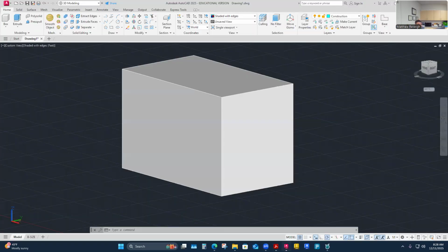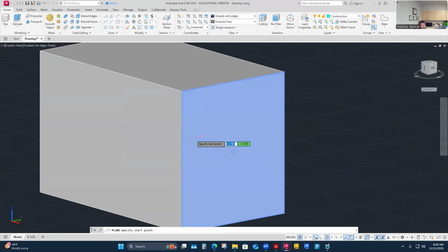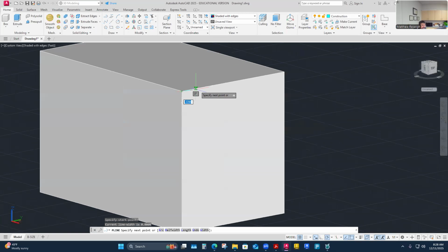So what I'm thinking is, on this surface, I'm going to cut this out, 1 and 3/4 by 2 right here, and I'm going to go in so far. I'll just do the sketch first. I'll do a polyline sketch on my construction layer on this surface, from this corner along this surface. This is the way that it's 1 and 3/4, right? 1.75, and then it's going to come down 2 inches, and then back this way to the edge, which I can just lock into a perpendicular grip here, and then back up to the start.